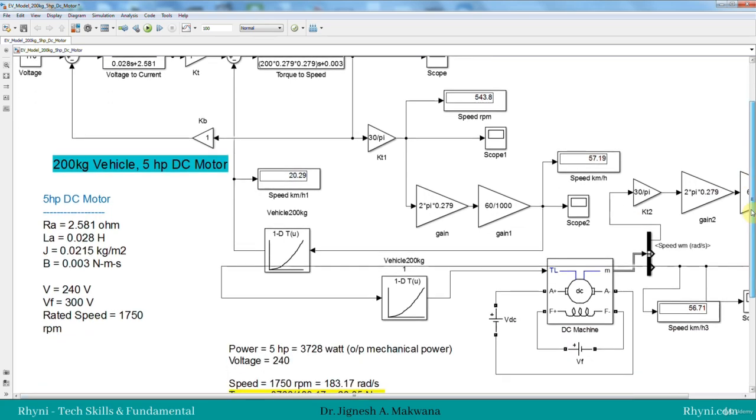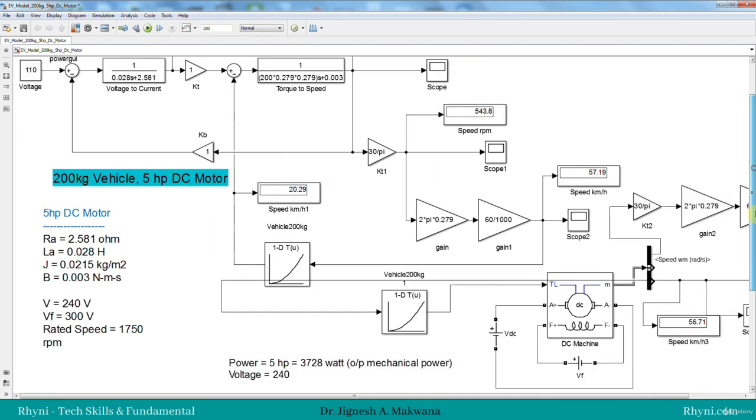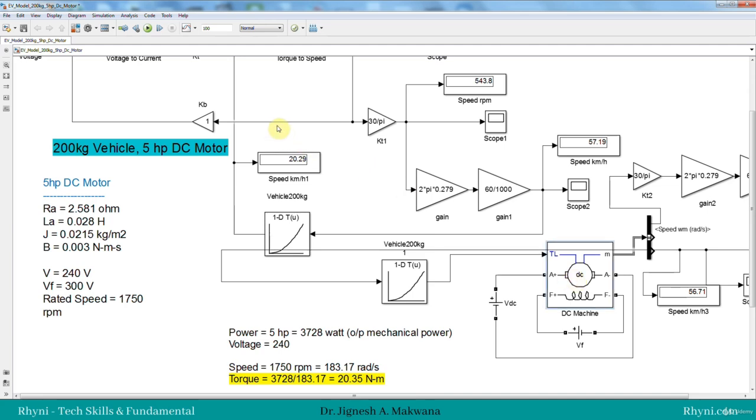So now you can understand why we need to select the particular motor. As we have built the vehicle model for the specific vehicle of the Maruti Suzuki Dzire model, the same way, when we have available the data of the electric motor that is used for electrical vehicle purposes only, you will find a number of electric motors in the market, and from their data sheet we can build the motor model in MATLAB Simulink. It will give us an idea, if we purchase that motor, how it will perform with our selected vehicle model.